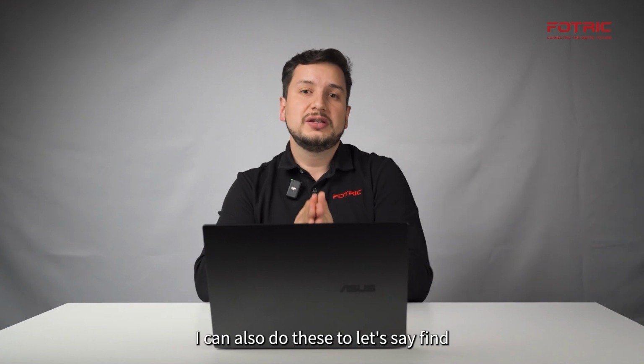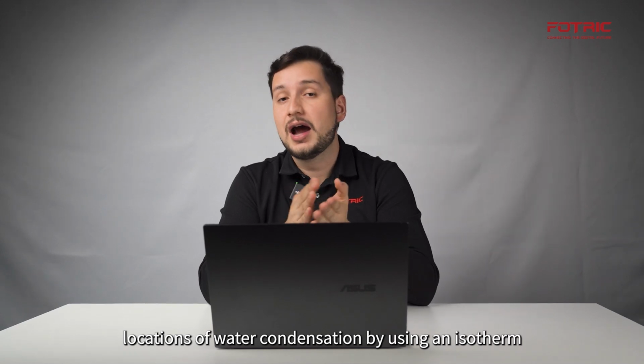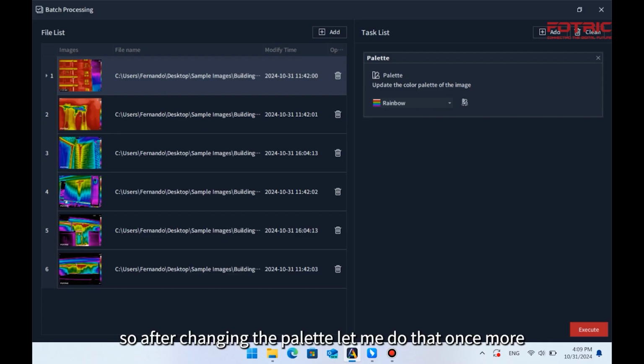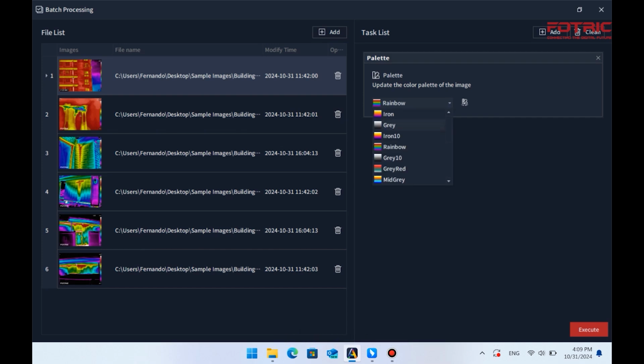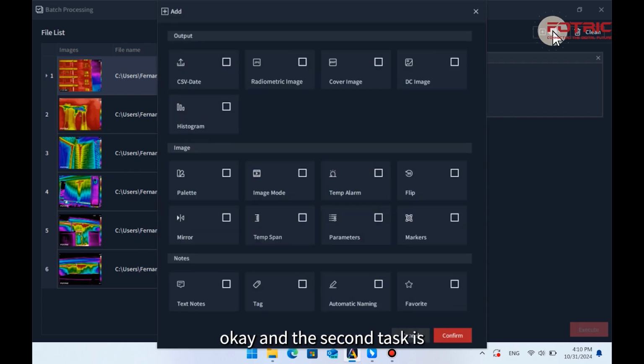I can also do this to, let's say, find locations of water condensation by using an isotherm. So after changing the palette, let me do that once more to show you. The first task is going to be to change the palette to gray, okay? And the second task is to apply an isotherm or temperature alarm.